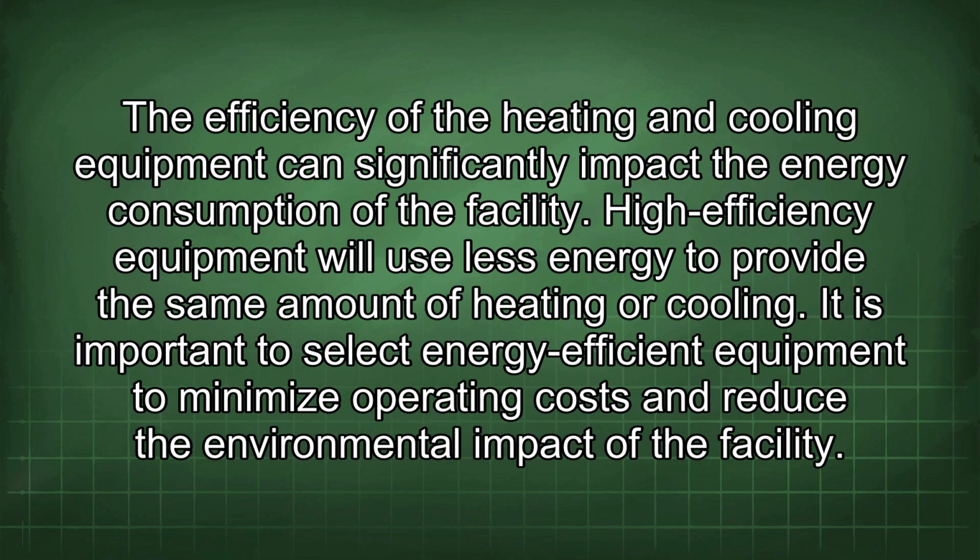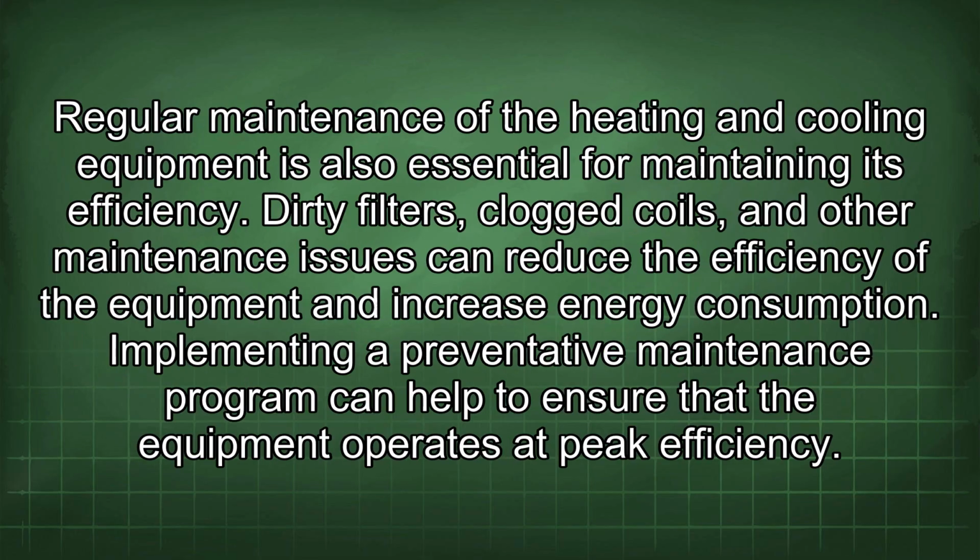The efficiency of the heating and cooling equipment can significantly impact the energy consumption of the facility. High-efficiency equipment will use less energy to provide the same amount of heating or cooling. It is important to select energy-efficient equipment to minimize operating costs and reduce the environmental impact of the facility. Regular maintenance of the heating and cooling equipment is also essential for maintaining its efficiency. Dirty filters, clogged coils, and other maintenance issues can reduce the efficiency of the equipment and increase energy consumption. Implementing a preventative maintenance program can help to ensure that the equipment operates at peak efficiency.